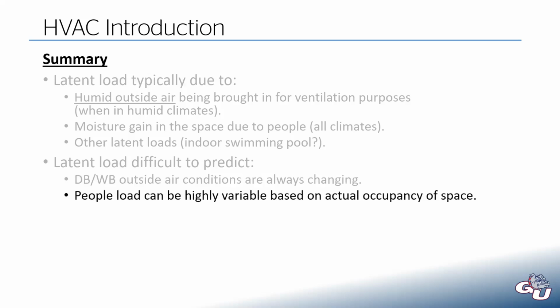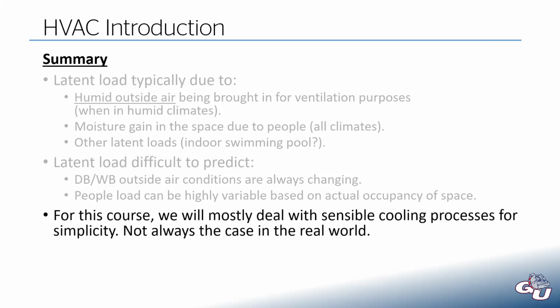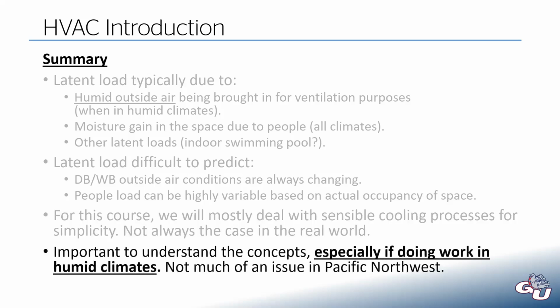Your people load can also be highly variable. Your space might be designed for 10 people. Well, how often are 10 people there? Maybe sometimes the room's empty, and maybe sometimes there's 5 people in that room. For this course, I like to keep it fairly easy on this topic. We're mostly going to deal with sensible cooling processes, just to keep things a bit simple. But it's important to talk about latent load, because in certain climates, that is a really, really big deal.